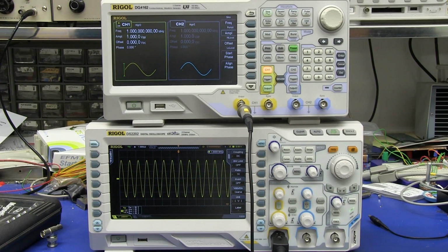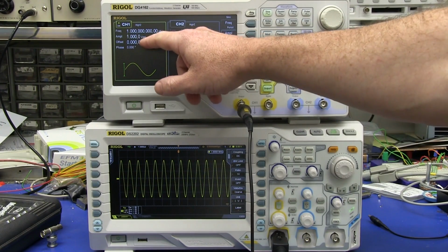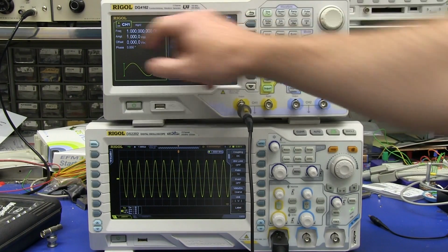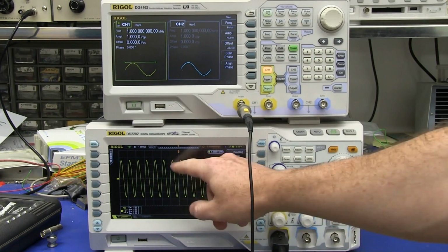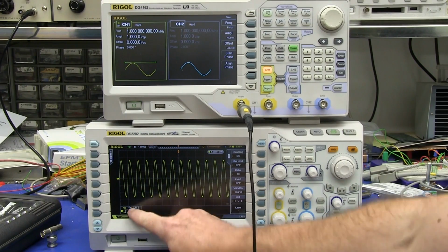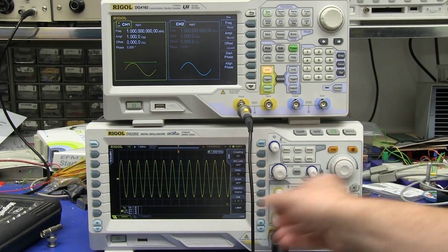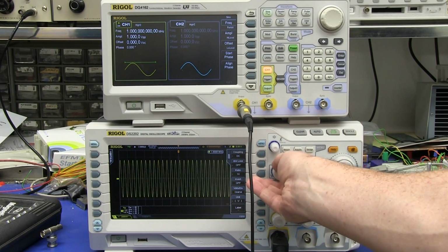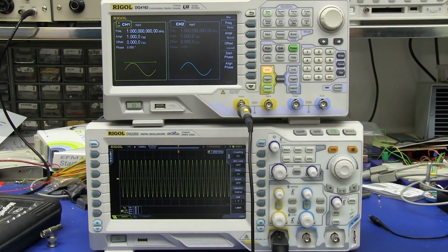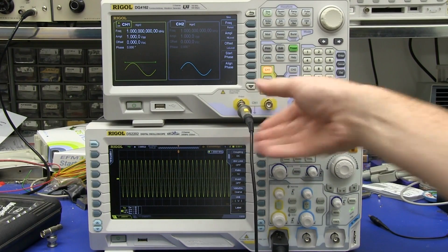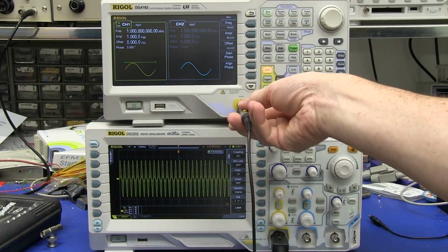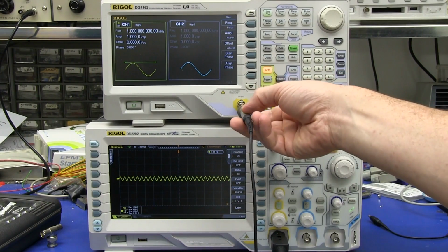Now, the first thing you should say is, well, bullshit, show us. All right, we've got our signal generator here, we've got our scope. I've got it set to 1 volt peak to peak, sine wave at 1 megahertz, so we'll be able to adjust the frequency, and there it is, 1 volt peak to peak. You probably can't see that down there unless you're watching in HD, but that is 1 volt peak to peak. Not a problem, right? At 1 megahertz, the probe really isn't introducing any attenuation at all. Bandwidth limit doesn't come into it. By the way, I'm on ×1 here with the scope probe. I can switch it to ×10, of course, and there we go, we get 1/10 the amplitude.